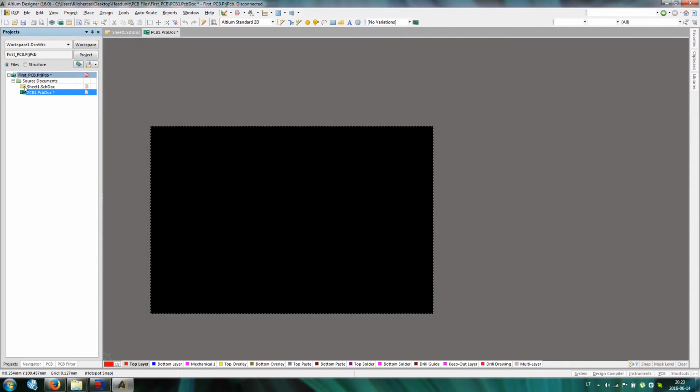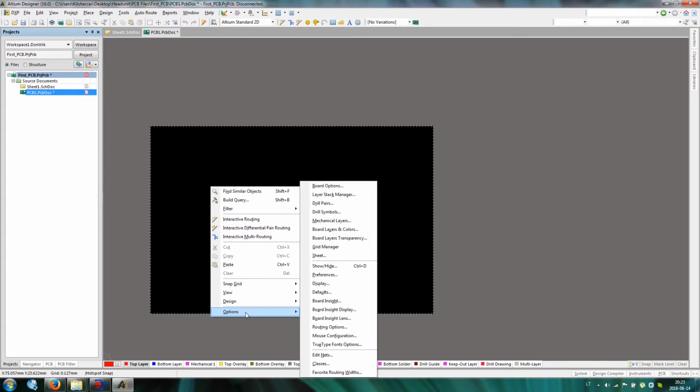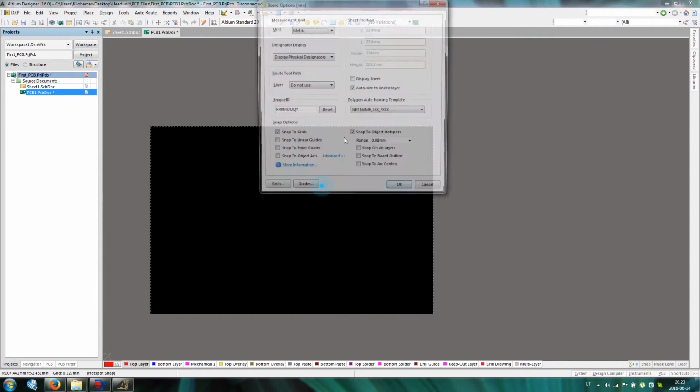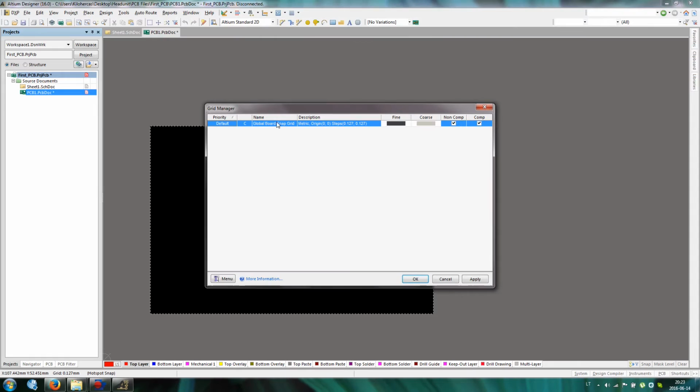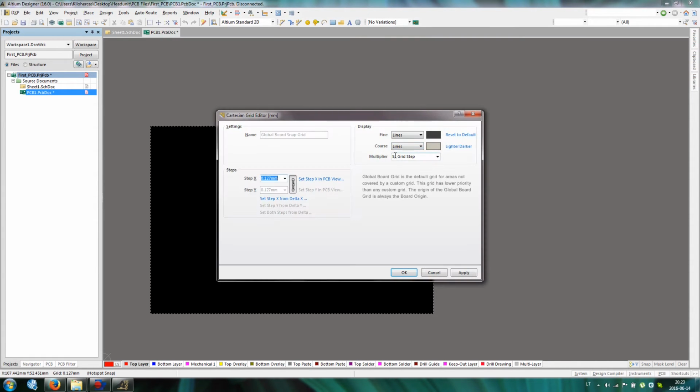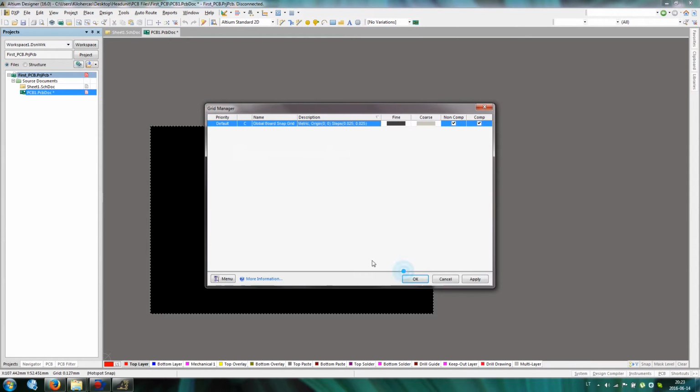What's rooms? Basically, if you have multiple circuits inside one project, it will create rooms with the different parts of your circuit, and you can work and copy designer and so on. You don't need that. Okay, let's go to the board options. This is my preference: I like to use grid size like this and distance like okay.